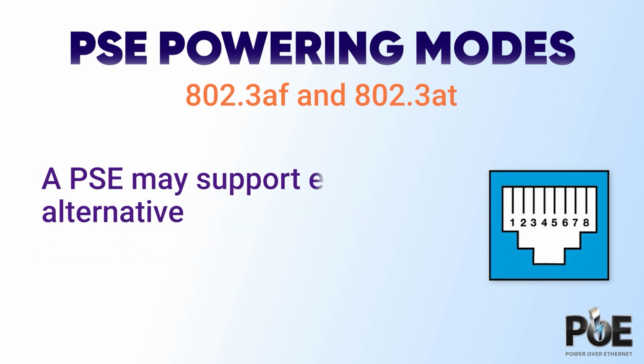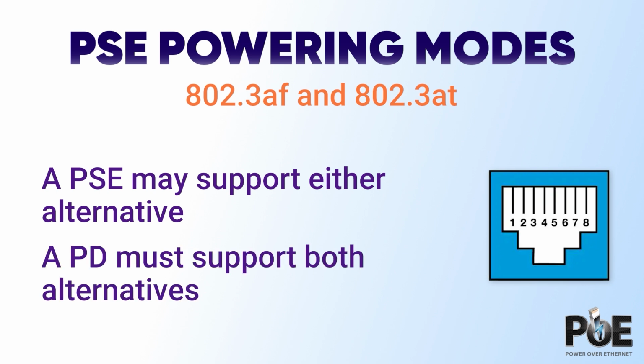To be compliant with standards, a PSE may support either method. A PD, however, must support both methods. This ensures interoperability regardless of which method is utilized.